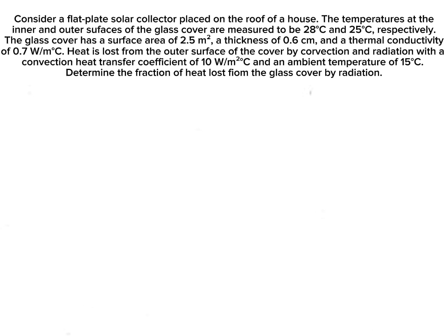centimeter and a thermal conductivity of 0.7 watts per meter Celsius. Heat is lost from the outer surface of the cover by convection and radiation, with a convection heat transfer coefficient of 10 watts per meter squared Celsius and an ambient temperature of 15 degrees Celsius. Determine the fraction of heat lost from the glass cover by radiation. So this is the given of our problem.